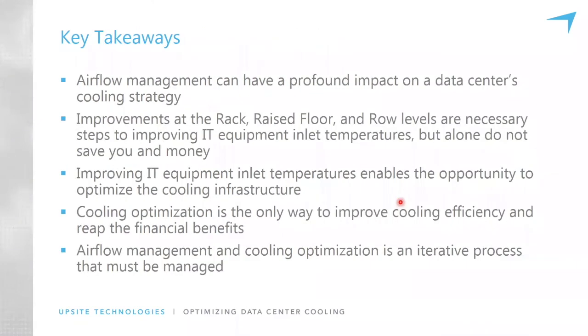So let's take a look at some of the key takeaways. Airflow management can have a profound impact on the data center's cooling strategy, the overall cooling capacity, and the IT equipment reliability. Improvements at the rack, the raised floor, and the row levels are necessary steps to improving IT equipment inlet air temperatures, but alone do not save you money. You've got to make those adjustments. Improving IT equipment inlet temperatures enables the opportunity for the changes to the infrastructure to realize those benefits.